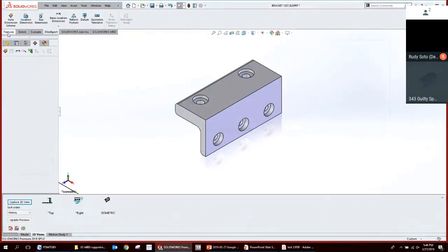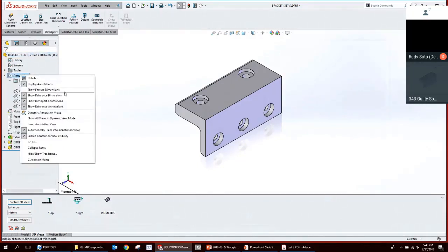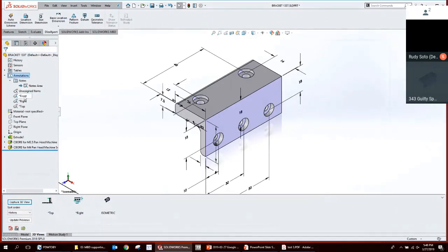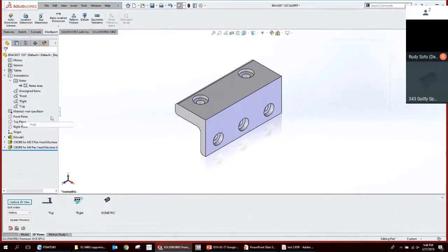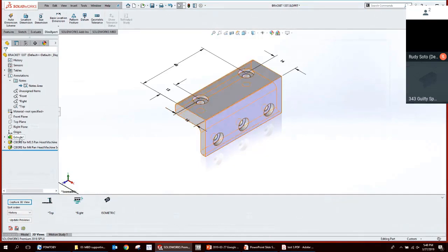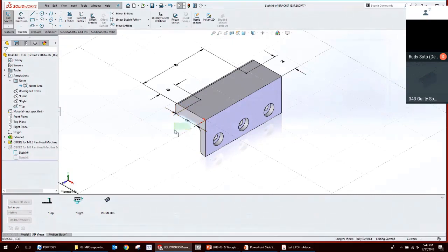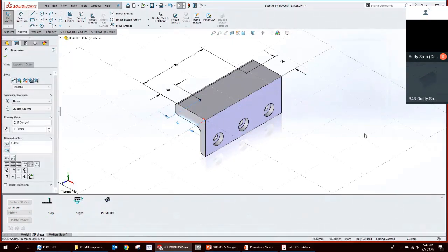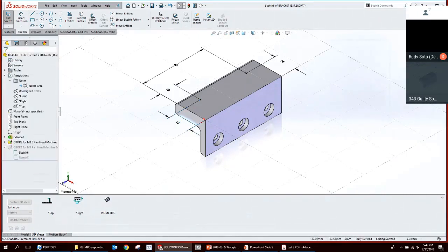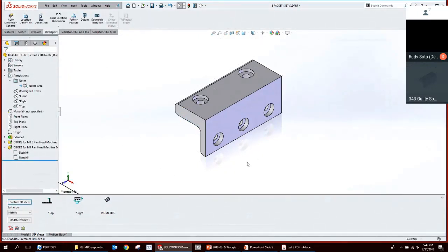So if I go back to the SolidWorks feature tree here, and I say annotations, show feature dimensions, there's all the feature dimensions, right? And I go through here and I hide these annotation views, and I start showing these annotation views again. You can see that SolidWorks has also taken this 16 sketch dimension, which is to the counterbores up top here, and it has assigned this dimension from that sketch to the top annotation view. Annotation views were actually there before DimExpert was there. And you could potentially do the same thing where you're setting up yourself in model mode.